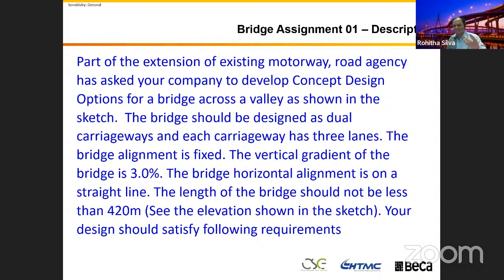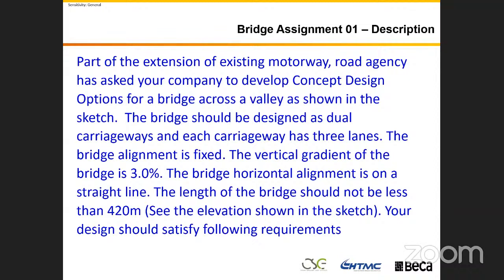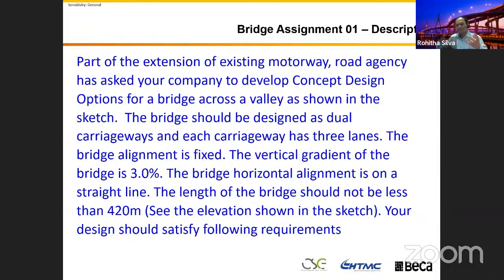What is concept design? When you design a bridge, we go through a few stages. One is the feasibility studies. You just go there and see, I want to put a bridge here, what sort of thing, whether I can do it, what sort of information we know. We call it REF, a review of environmental factors; I think different countries use different names. For example, utilities, geotechnical investigation, heritage, environmental impact, all those things we review. We develop a report, and that report we submit to a company and ask them to develop the concept design.